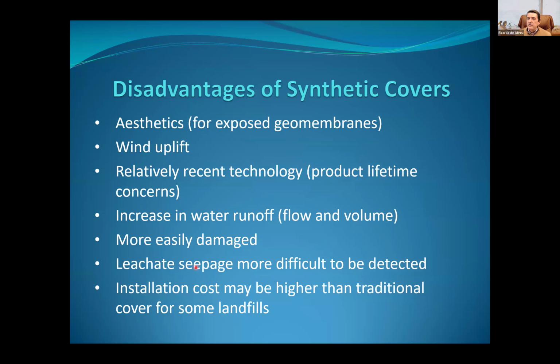To be honest, we also have to put the disadvantages of synthetic final covers. One is aesthetics, especially for exposed membranes. If you use black HDPE, it's not going to look great in your landfill. It does the work, but it won't look great. The other one is wind uplift, so you have to find ways to anchor the synthetic cover. It's a relatively recent technology. There are product lifetime concerns. I'm going to go over that in a few minutes.